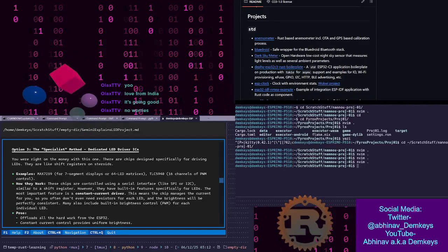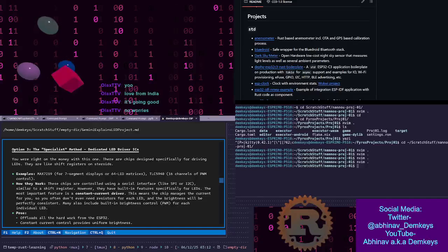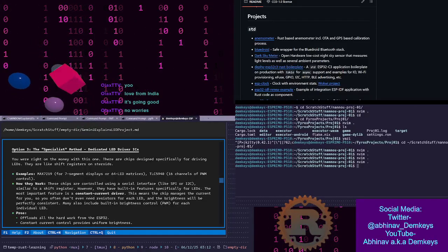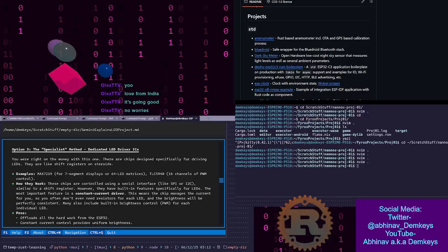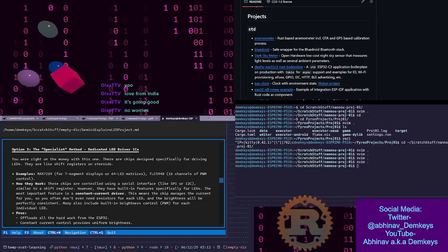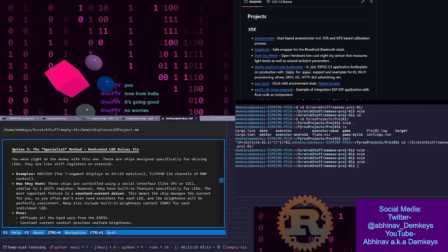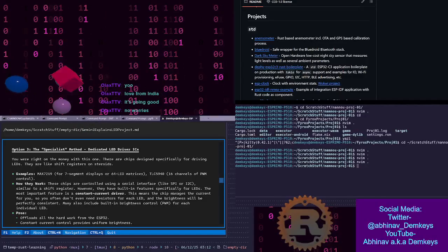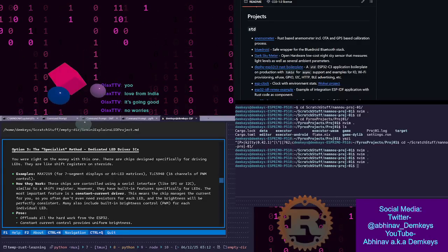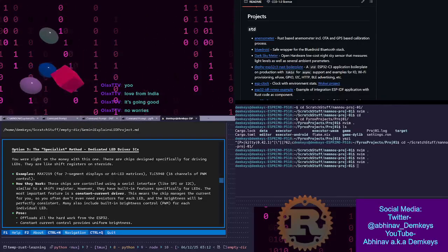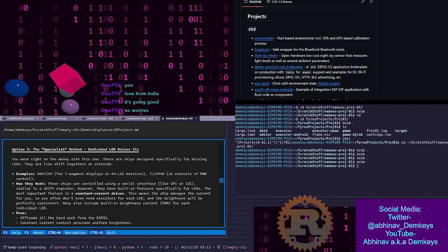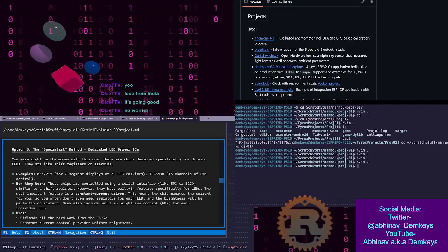The entire thing is actually able to power the controller itself. It also has the functionality for powering the entire strip, because you connect an adapter that comes with this entire kit, I forgot if it was 12 volts or 5 volts. You hook that into your wall socket, which in my case is 240 volts, and then that gets stepped down to either 12 volts or 5 volts, and that is powering this IC, which is then driving the LEDs.